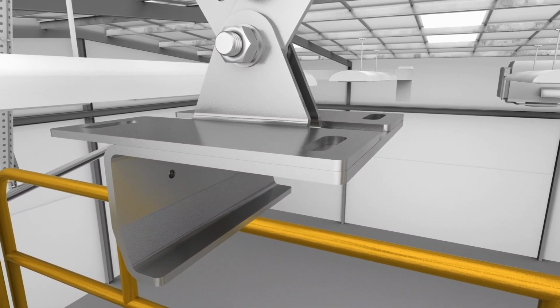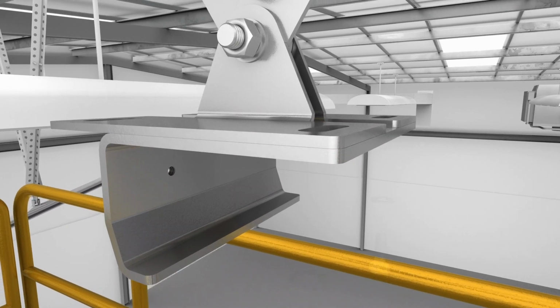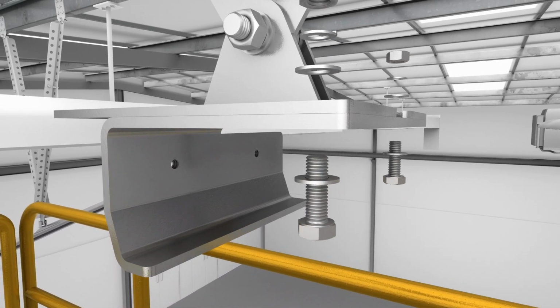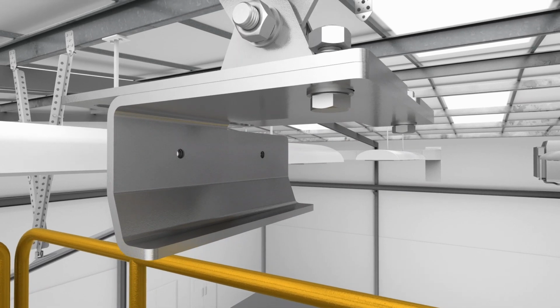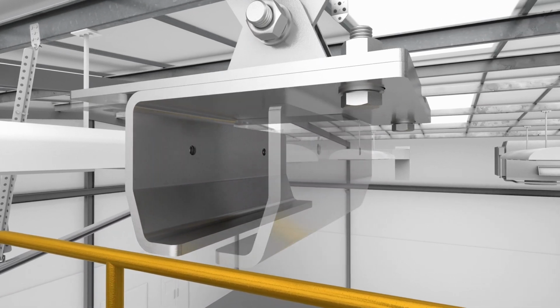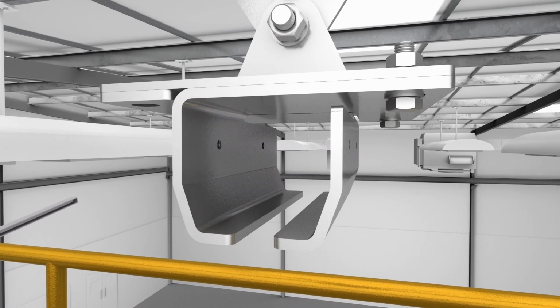Attach a single half clamshell bracket to the underside of the slotted clamshell top brackets and secure into position using 2 M12 40mm bolt assemblies. In total, the clamshell assembly consists of 2 half clamshell brackets that clamp the rigid rail into a captive position.